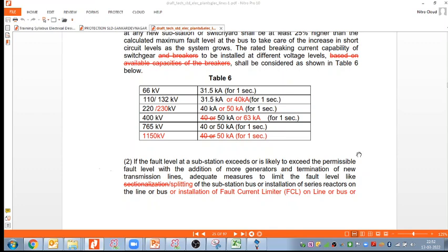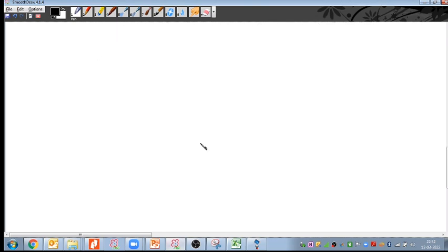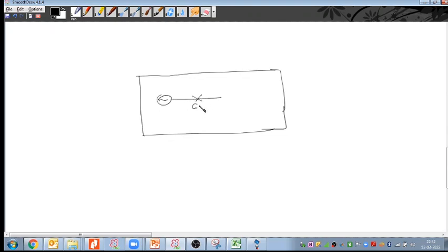Okay, so you are telling that we divide the MVA with the percentage impedance, and then we get the fault current. What will happen when it comes to the generator generating substations? There is a generator site: we have the generator, and after that the generator circuit breaker, GCB, and we have the CT and VT also. Then it goes to the GSUT, the generator step up transformer, and from that we step up the voltage and feed to the transmission line.